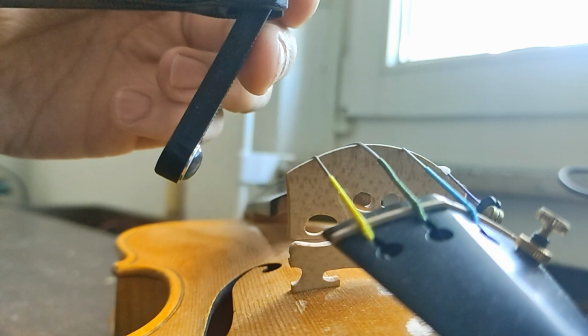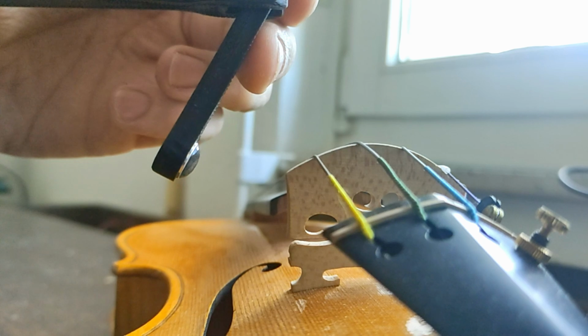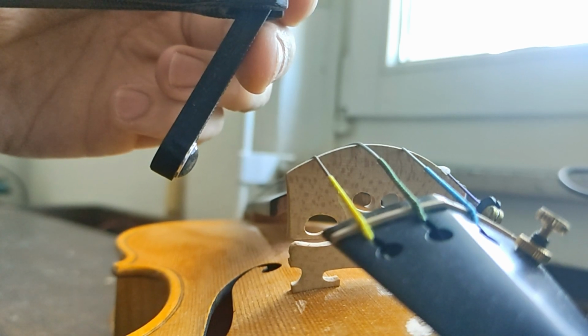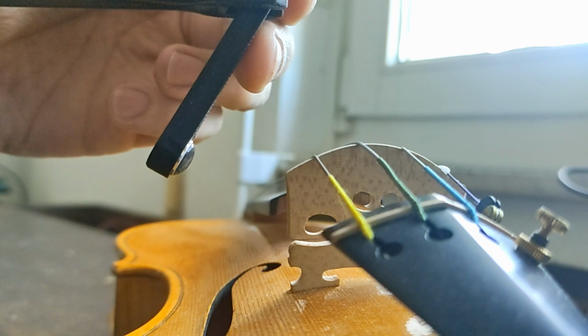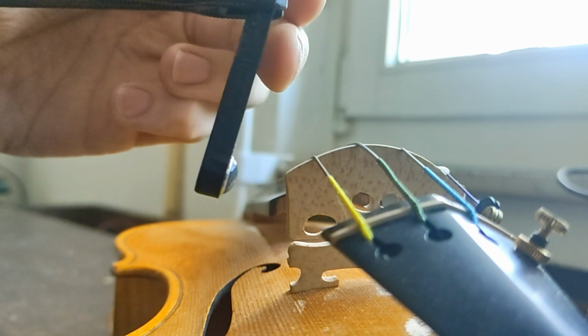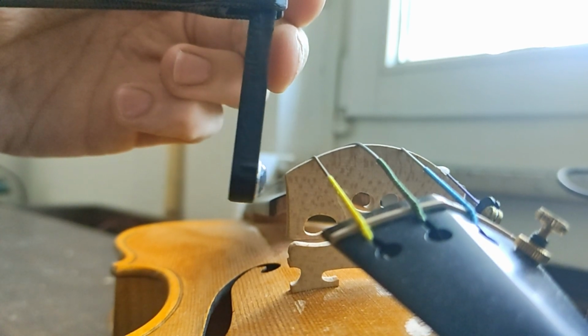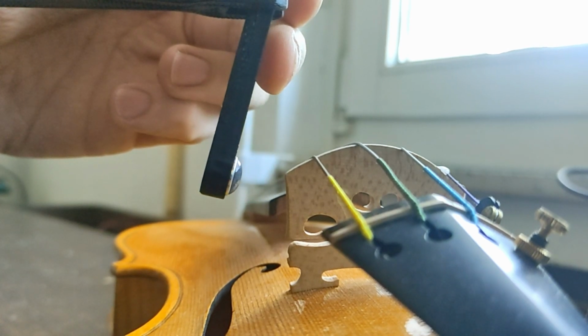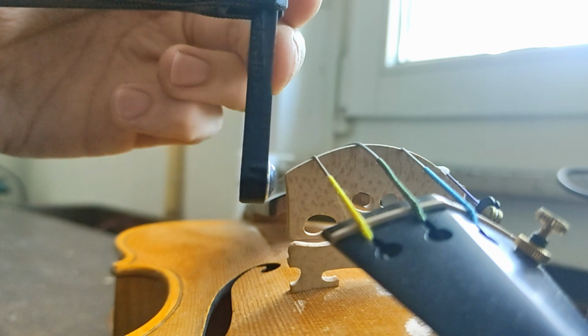And here you can see the hammer hitting the bridge in slow motion. You may be able to tell that the contact time is not 0. To get closer to this theoretical ideal, we could either increase the hardness of the hammer tip or that of the object we are hitting. The excitation signal of a steel-tipped hammer on a steel object actually turns out to be completely flat up to very high frequencies. Okay, almost done with preparations.